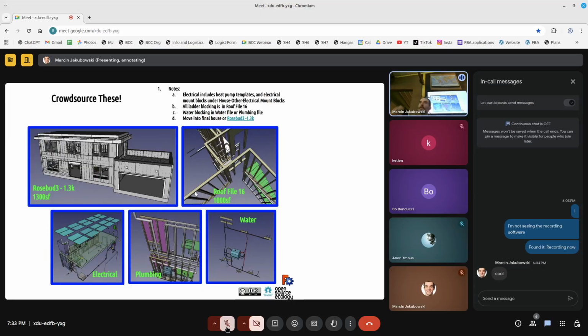The standard one, which you poke it in, is a stab kind of fitting. It's not a lever like these Levitons. And the ones that you stab in the back, yeah, there's issues with them because sometimes you burn houses down with that. This is a different mechanism. It's actually a solid lever. Interesting. Okay.